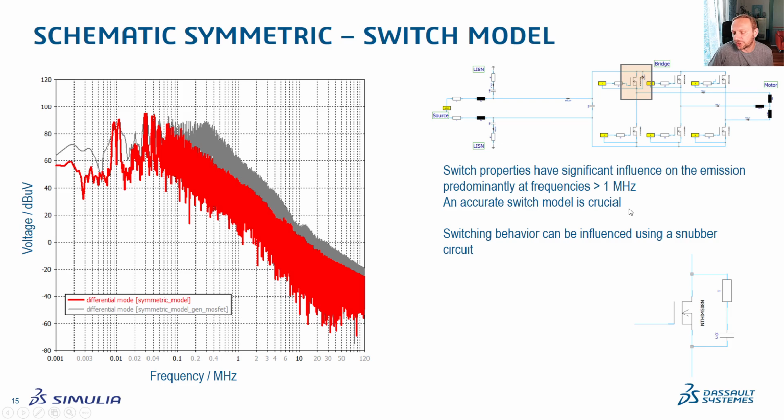It's always a good idea, and what's always done in EMC in order to improve your EMC behavior, is to keep the current loops as small as possible. That's a general rule. So by adding this capacitor and this resistor around the transistor, I make sure that the high frequency current loop stays closely confined to the circuit around the transistor and reduces this emission.